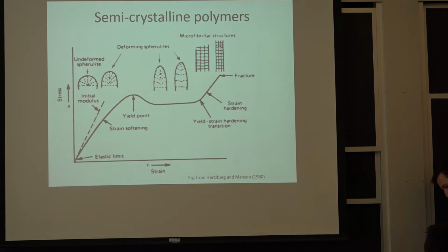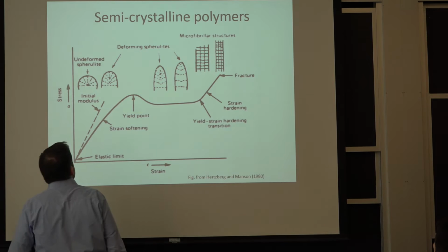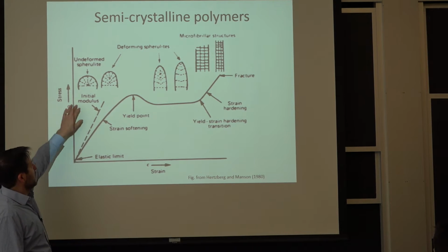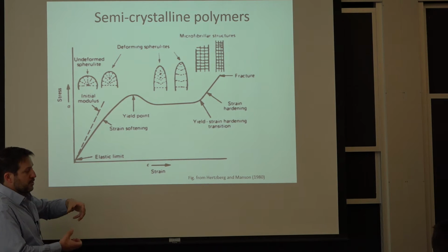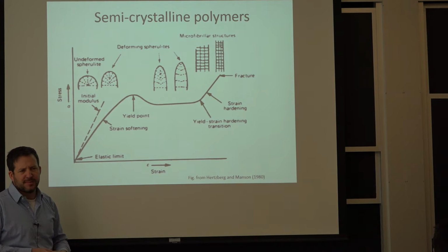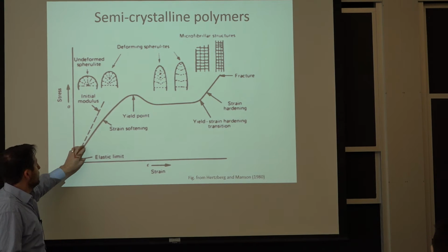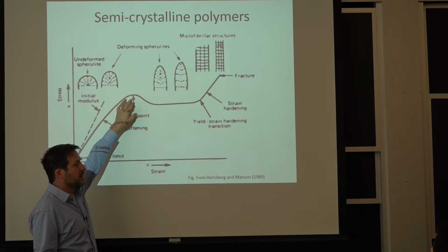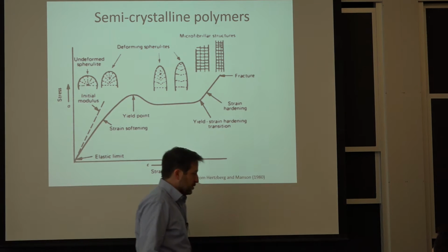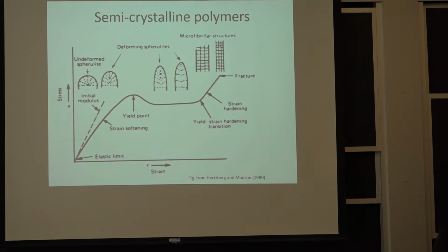So this is really in a schematic, again, trying to make sure you'll remember for a while, hopefully forever. You have the spherulite, and of course, initially it's a little bit of a viscoelastic behavior in the case of polymer, and we'll go to that. You don't have to worry about that. So it's going to deform a little bit. Eventually, it starts yielding. So what's unique with the plastics, a lot of times, instead of having that stress-strain curve for steel, so I'll draw a steel one. This is appropriate right here.